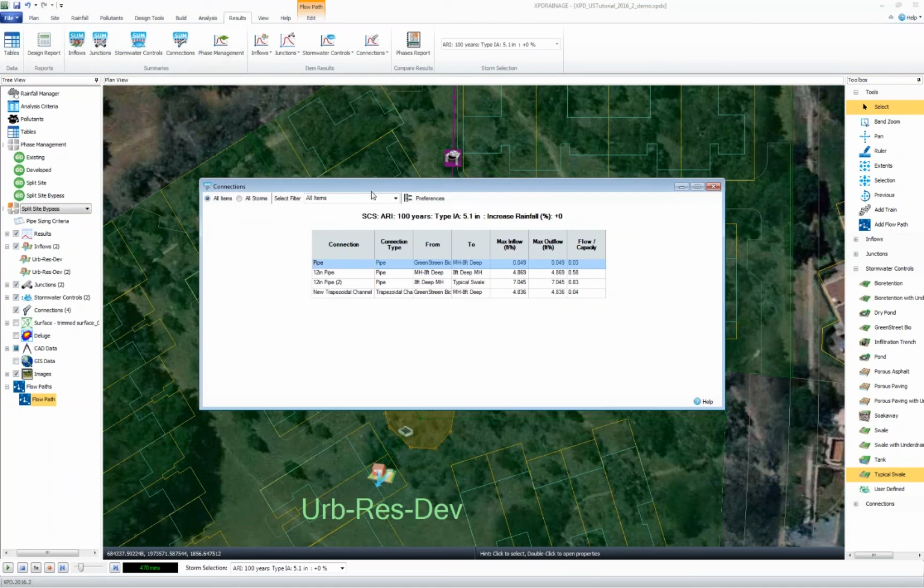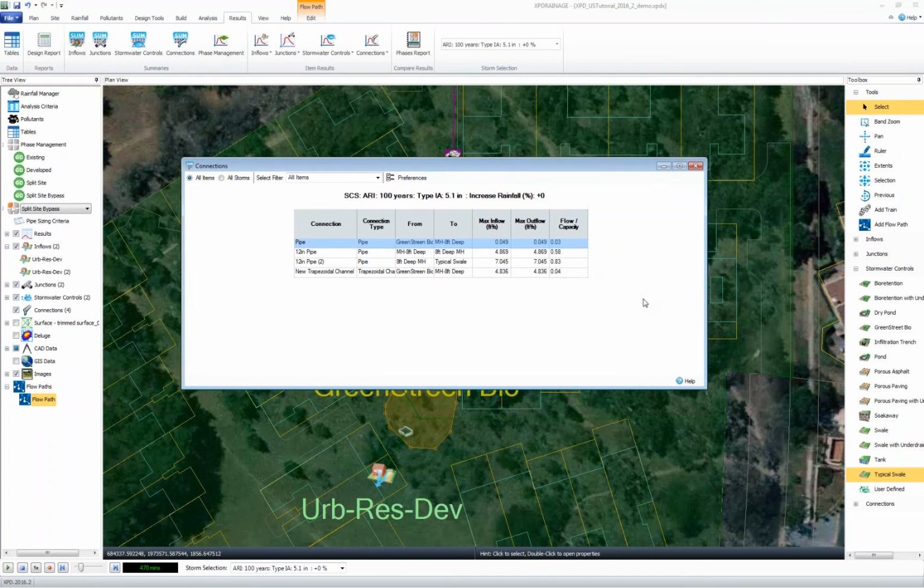Another one, again, that pipe sizing seems like everyone does. So what do we really look at? I would say that first and foremost, people are probably going to look at a flow capacity comparison. Again, how much flow is getting through that pipe, and what is the ultimate capacity they can hold. When that gets to be about 1, that's probably not a very good functioning pipe size. You want to maybe make it bigger. I've even seen people go with the rule of thumb, 0.8 flow capacity, maybe bump that up 1 size.